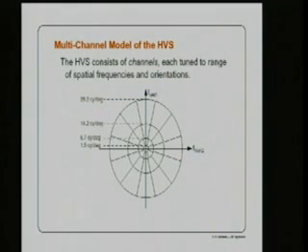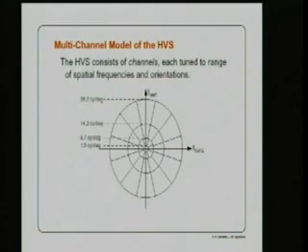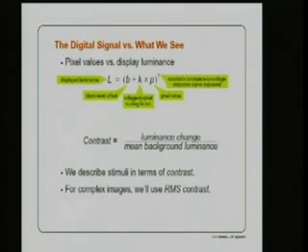So what we see in common with the previous slide is as we get out from the origin, the pass bands of the filters are bigger, right? What we don't see in common, there are no squares here, right? You will never get these pie-shaped wedges from a separable filtering operation. Nevertheless, we as signal processors still like to say, gee, this is close enough to this. There's the laziness factor. So just remember this. The next time somebody says, we use wavelets because it's well matched to the brain, no, it's really not. So give them a good heckle.